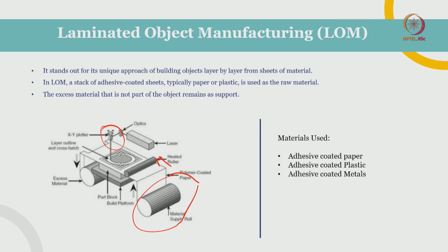forming new objects. Okay, and this head, this feeder, will also have an inkjet head, so it can spray different colors on that laminated sheet. So you will actually get a very good high definition color print out of this printer. Okay, then what about support materials? This paper itself will act as the support material, and once the entire printing is done, you can simply remove the printed object from the print base, and then remove the support material, exactly like how we do in our FDM printer.